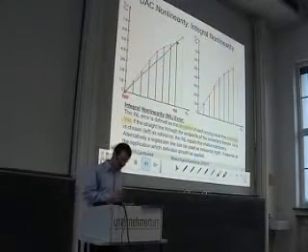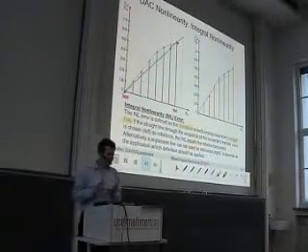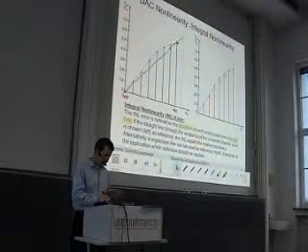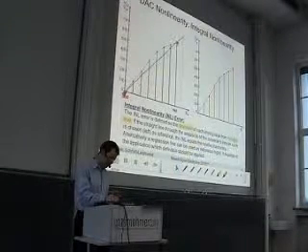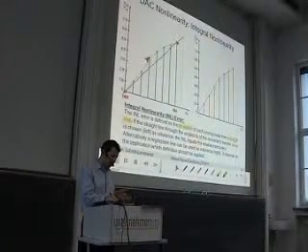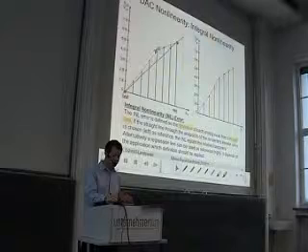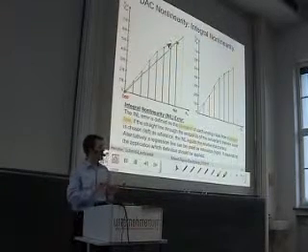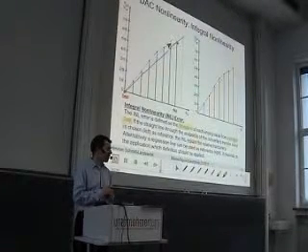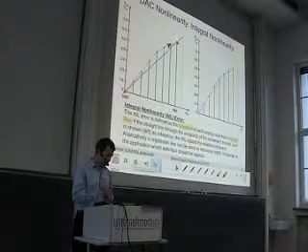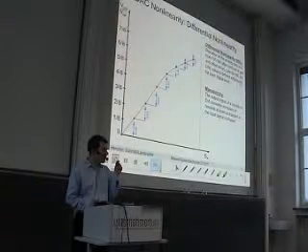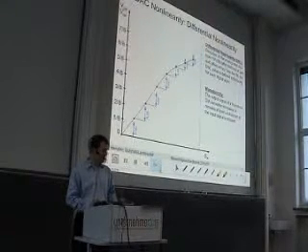If we look at the integral nonlinearity, you can see that this is a global measure for nonlinearity. For instance, we start here with a very small value, and then the nonlinearity increases, we get further and further away from the green reference line, and here we come back. So this is somehow a global measure because local effects are accumulated. In contrast, the so-called differential nonlinearity looks only at the difference between two subsequent points.